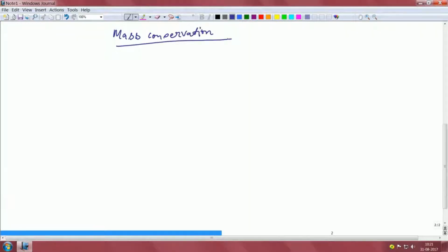This is important. If you observe, let us take any arbitrary control volume. This is a control volume which can have multiple inlets and outlets, correct. So, there can be some inlets, some outlets, that means mass is entering into this control volume through multiple ways, and the mass inside the control volume can be allowed to change.